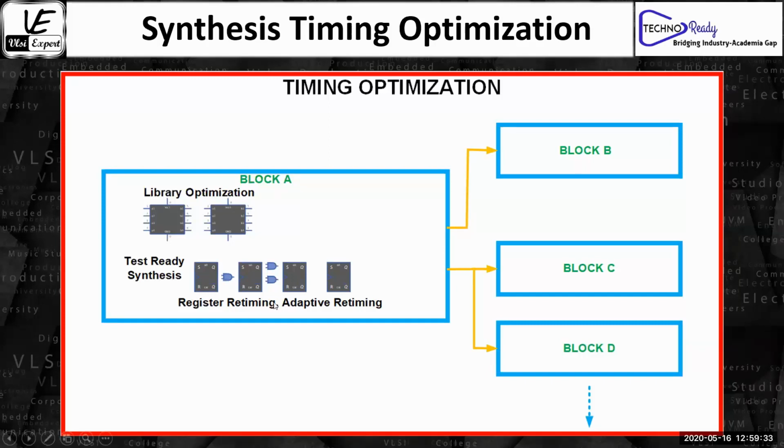Then another thing which we would look at is, suppose we have a logic where you have multiple flip-flops chained together with logic blocks in between. This is usually called pipelining, right? That's how a typical digital design is done. You have logic blocks which you break down into multiple cycles, and you put flip-flops so that you capture timing after each and every operation so as to best meet timing.